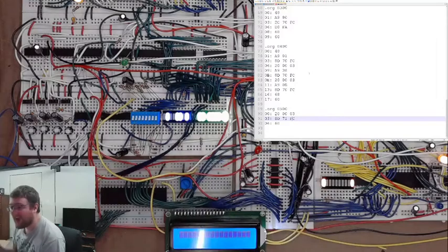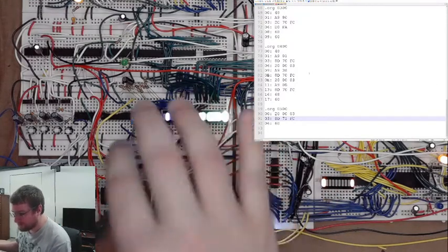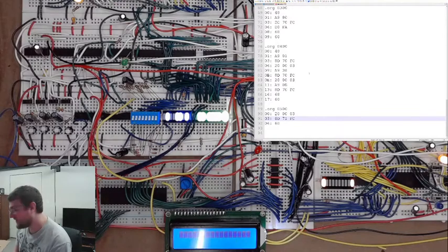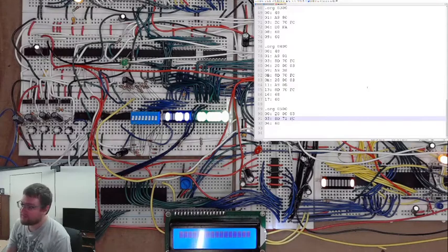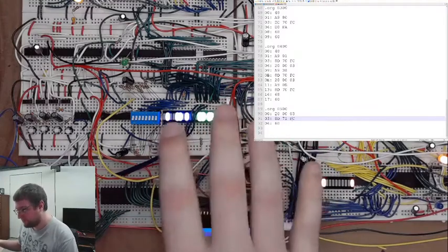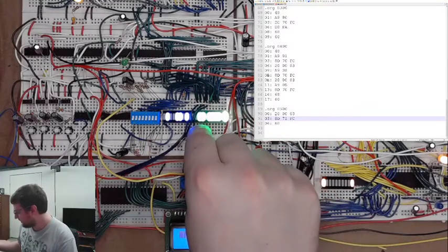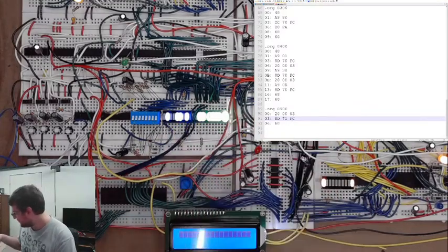But yeah, they can actually get brighter. Okay, these are already dimmed down. They can get so bright that it hurts my eyes, let alone a camera. It would just wash it out all the way. But this is the lowest amount of exposure I can get on this camera, and this is my more expensive camera. So in order to get any lower, I literally have to dim the LEDs by changing the drive resistors. And maybe I will, so that you guys can see it a bit better.